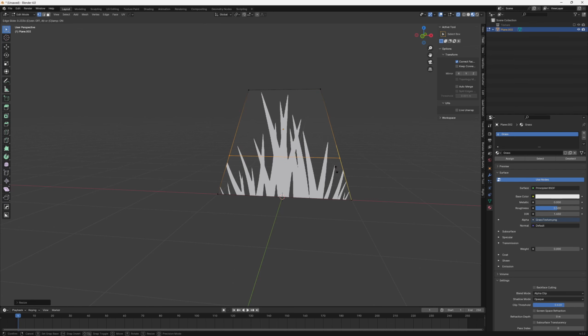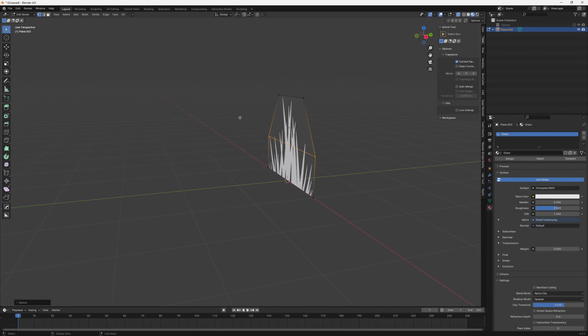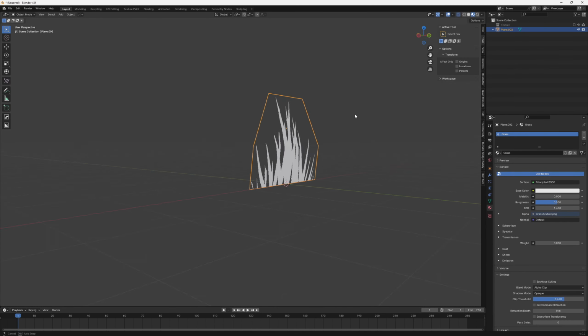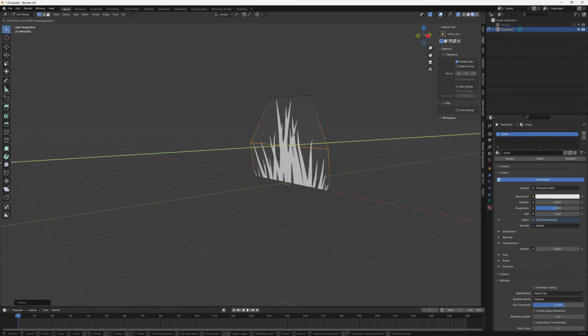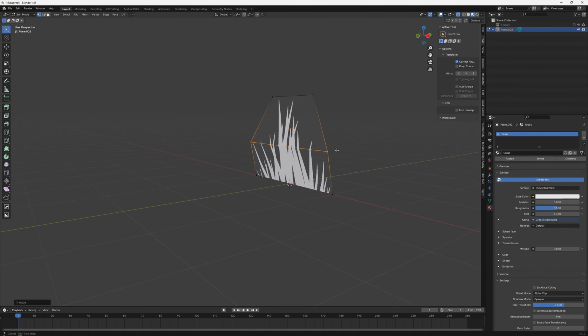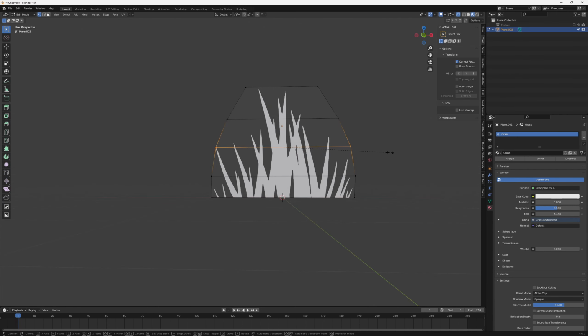I think it's worth one loop cut here to extend to keep our whole texture in, and as well we could even push it a little forward to give our grass some depth. And I do kind of like that. In fact, because we're working with a low resolution texture, it's all about trade-offs. So with less texture res, I might bevel it and give it 1 or 2 more bevels. Then I might extend that a little bit just to keep our texture safe.